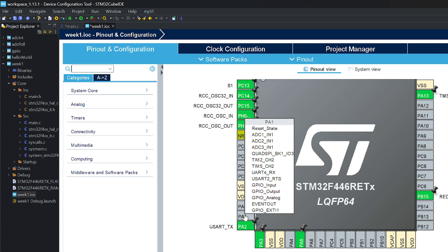We can use just one and have up to 16 channels and have it read all 16 different inputs of some sort. One A to D converter cycling through the channels and reading all of them. Yep. You have to set separate cells for the ADC. Oh yes. Okay. Yes, we're going to have to do all of that.